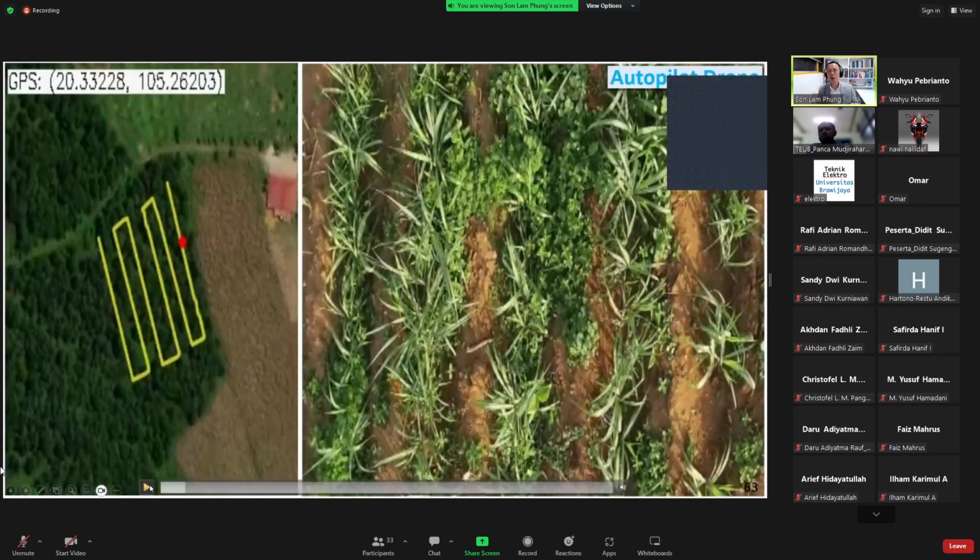If you take individual photos, you probably have to fly the drone very slowly. But if you take continuous video, you can afford to fly the drone faster, because in 1 second you will have 25 video frames, and you don't need to use all of them.